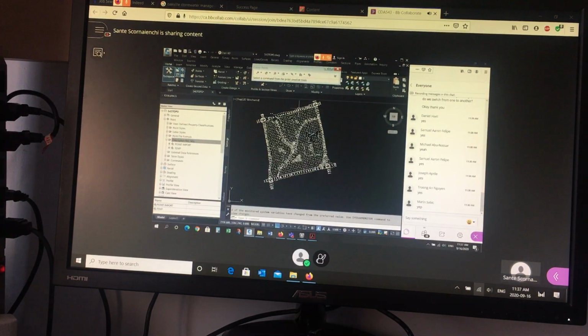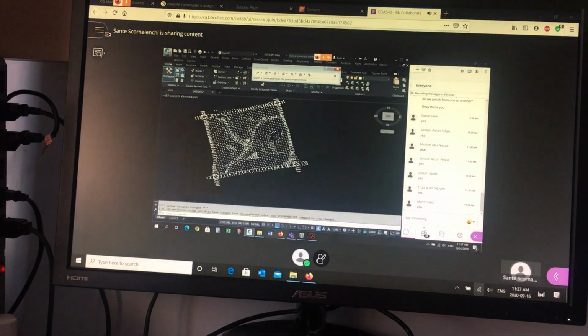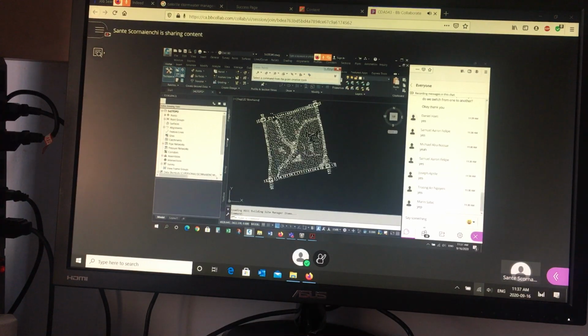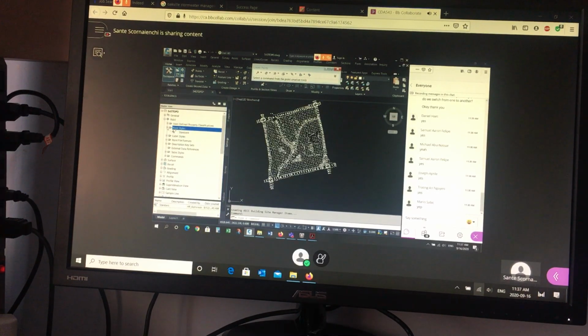Excuse me. Again, I'm going to start right from scratch. So I'm going to go to my tool space. I'm going to leave Prospector. I'm going to go to the Settings tab. I'm going to go to the Point Settings, and I'm going to go to the Point Styles. So usually, by default, there's always one style all ready to go. It's called the standard style, right? Label style, there's one called standard. Table styles, there's one called standard. There's always one ready to go. So the quickest way to get started is to make a copy of the standard one and then modify it. So that's what you're instructed to do as an example in the PDF.